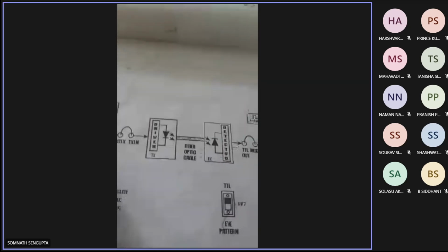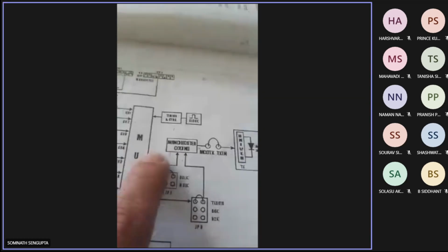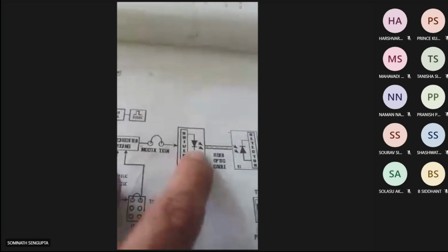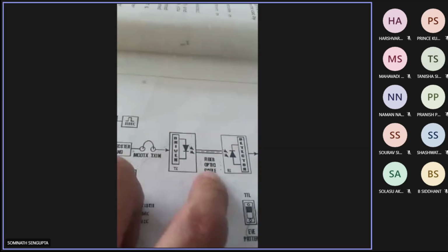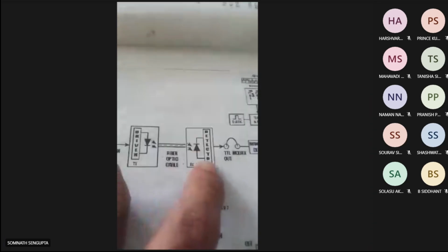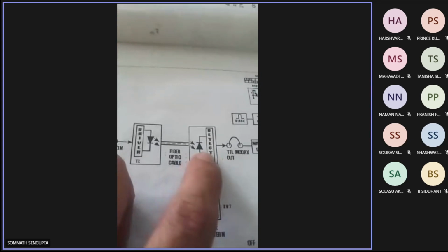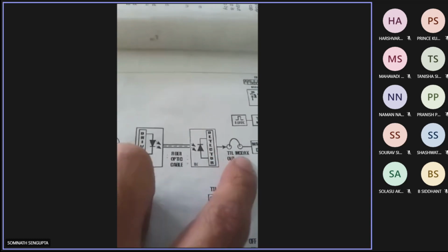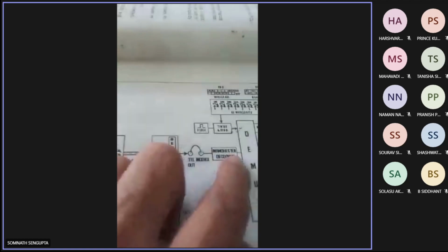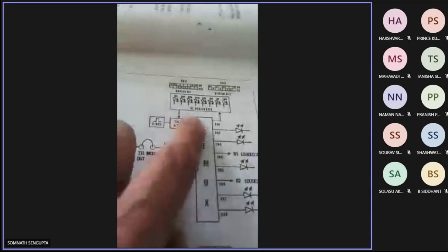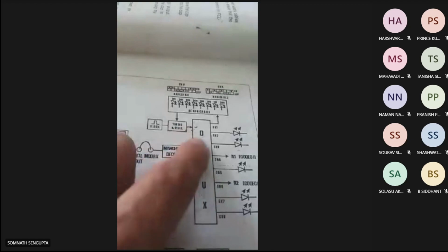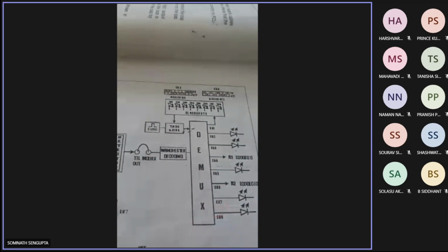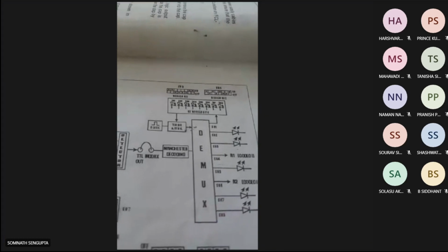The data is multiplexed, then Manchester coded and transmitted through the optical fiber cable. It goes to the detector, and after that to the receiver, where it is Manchester decoded and again demultiplexed, and further we get the signal from each channel.